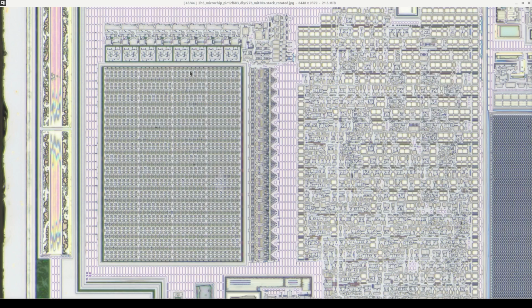It would be ludicrous to create an array that was the entire height of the chip and only a few microns wide. So to work around this, typically we use fewer rows than the logical memory depth and more columns, and then put muxes on the columns to select the actual bits we care about out of the entire physical memory row. And so in this case, we have a logical structure of 128 by 8, a physical structure of 32 by 32. And so if we have an 8-bit data bus and a 32-column physical structure, that means that we have a 4-to-1 column mux.